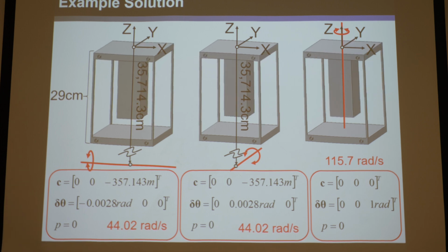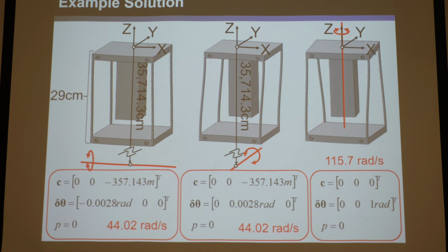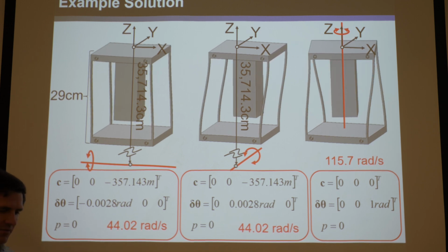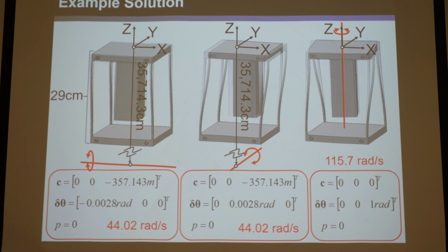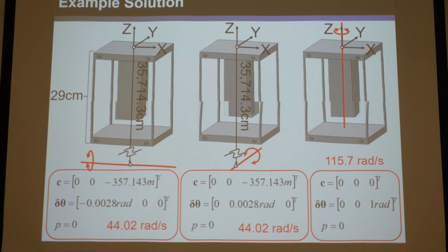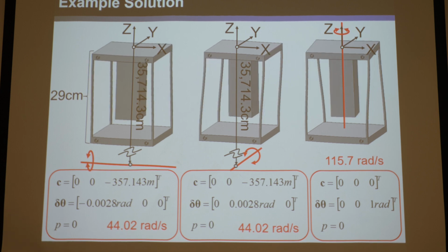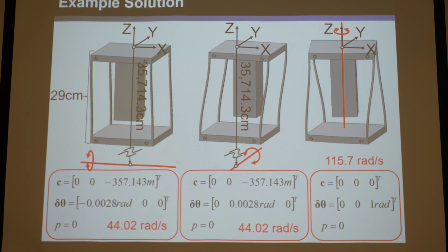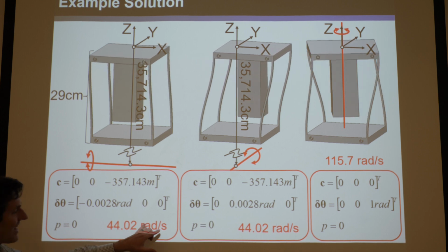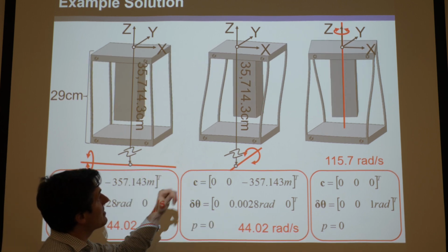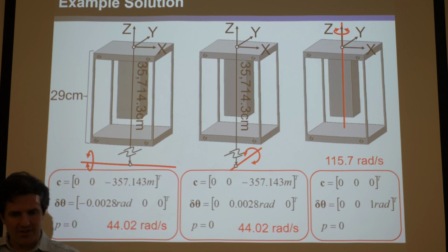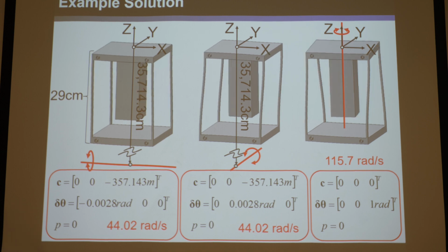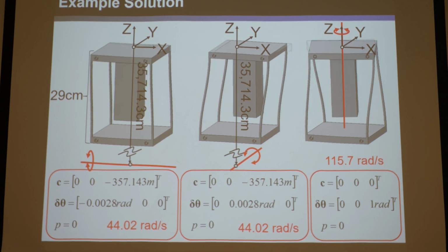Some atoms are going to be slightly different on one side than the other, and even with FEA, unless you take great care to mesh everything so that it's all perfectly symmetric, you're going to get slightly different values, because the meshing algorithm is going to throw off your symmetry. So if you did FEA on this, even without the bolts throwing off the symmetry, you'd have slight differences in these because the meshes aren't going to be symmetric. But of course, our analytical approach is perfectly symmetric, and it doesn't know the difference, so that's why they're identical.